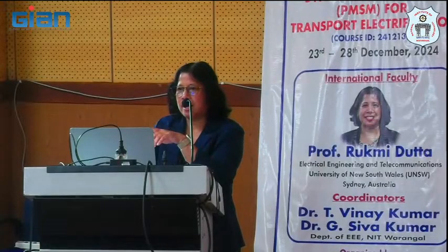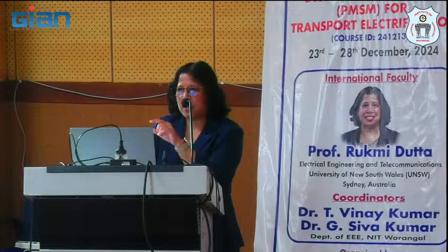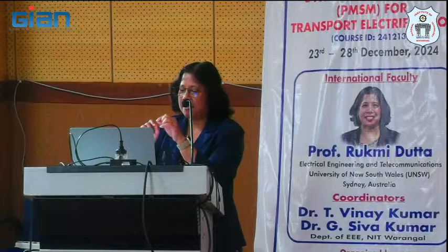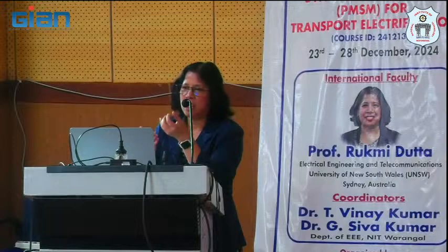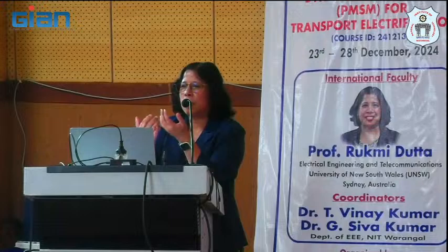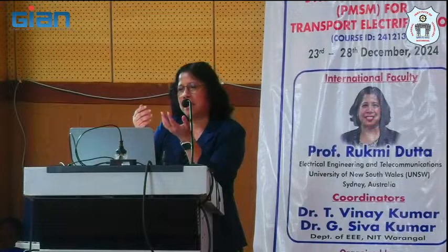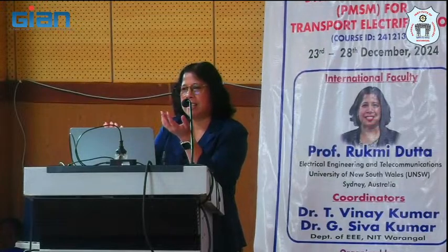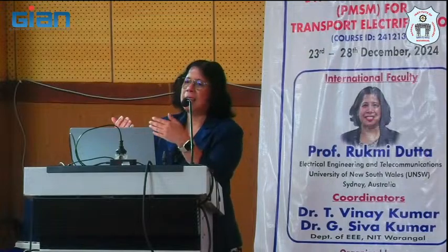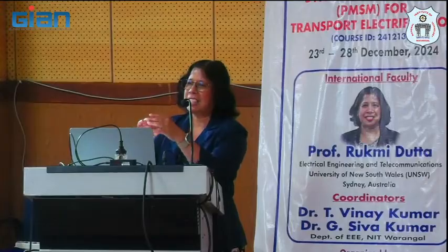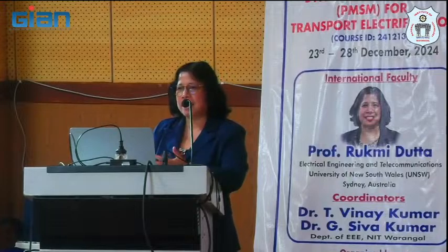With an encoder, you have no problem starting. Because if you have an encoder and if you are doing FOC, V and F increase in proportion. So if you have zero speed, it means your frequency is zero, voltage is zero. Next, let's say you go to 1 RPM. So 1 RPM, whatever the equivalent frequency, and you increase the voltage equivalently, right? So this happens through your FOC itself directly.